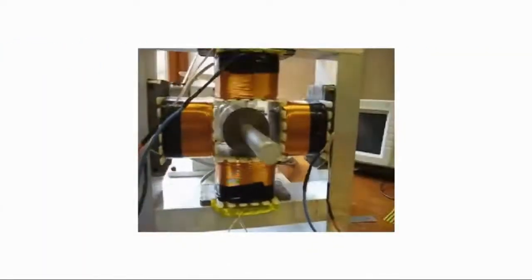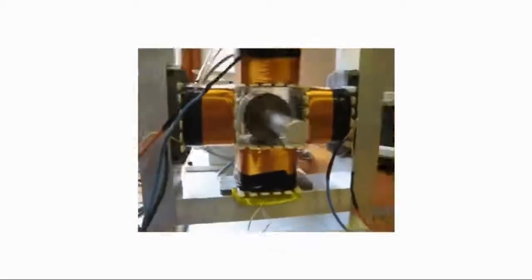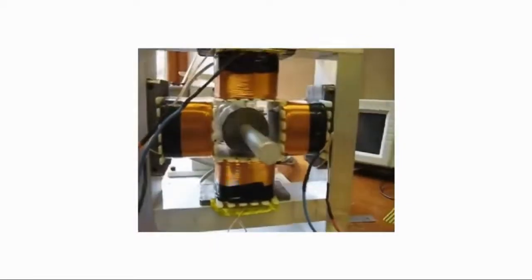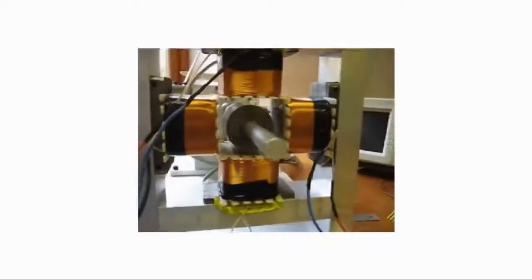While a wide variety of magnetic bearings have been developed, only one type has been widely accepted in the industry so far: active magnetic bearings. This is because an active magnetic bearing can exert higher density forces on surfaces of supported objects than any other type of magnetic bearing. They can also operate in a wide range of environments, and their properties can be made highly configurable through software parameters.